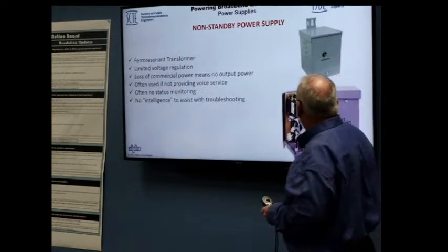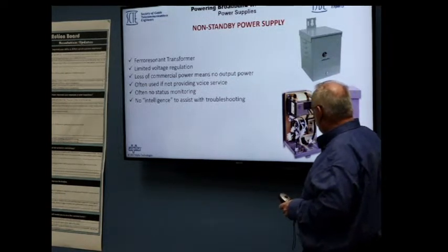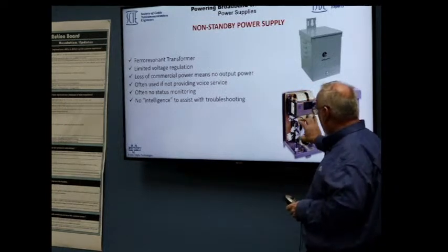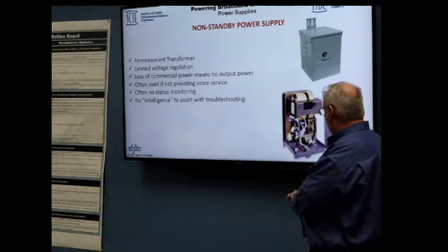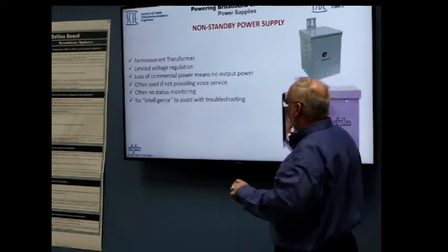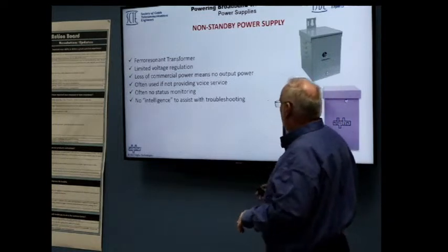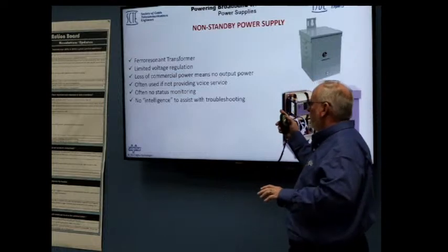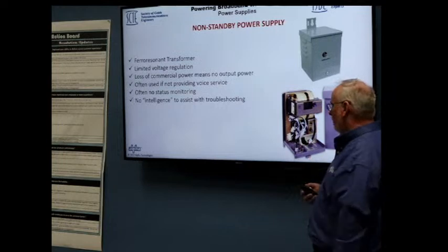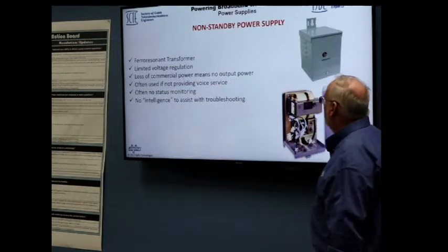So the non-standby ferro does the same thing. Again, there's different brands and stuff. It's effectively just a ferro, which is a transformer with an isolated load winding and a capacitor that creates the 90 volts. No standby with this. It does do some limited line voltage regulation because of the way the ferro works. It's often not used in voice service because there's no standby. 911, as soon as you add that, you have to add batteries. There's no intelligence, no status monitoring.